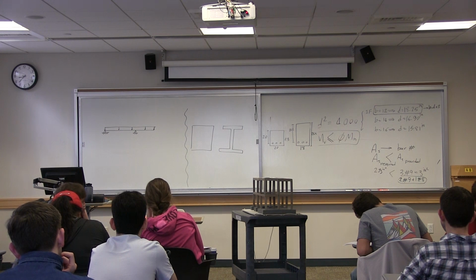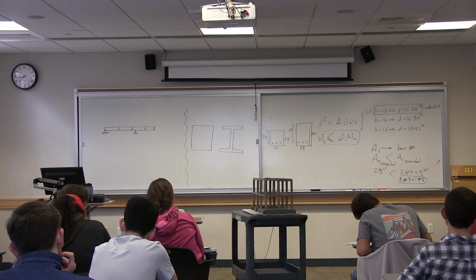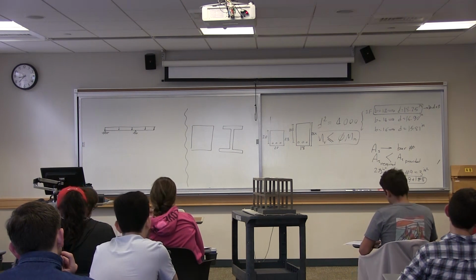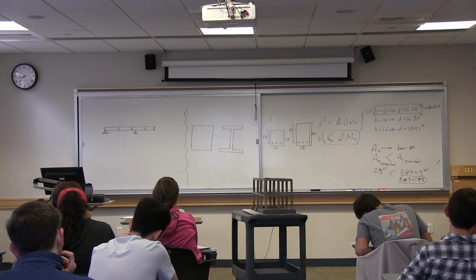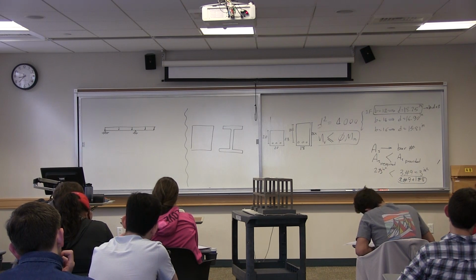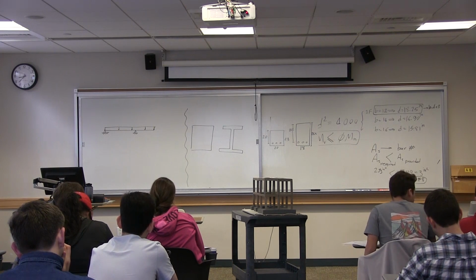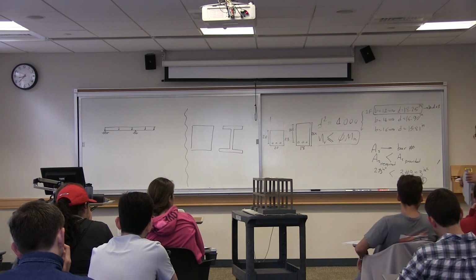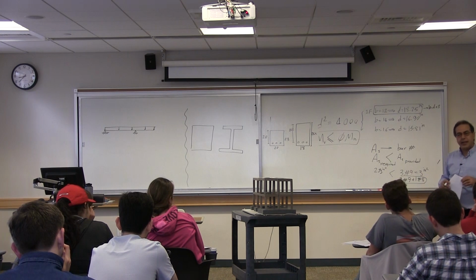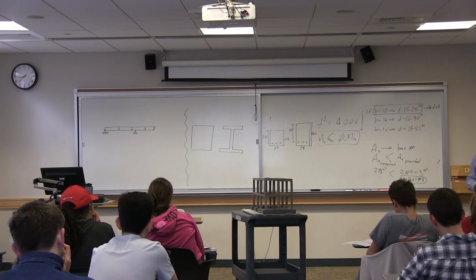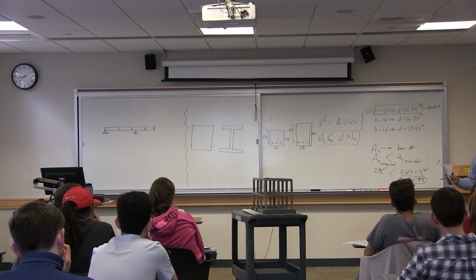When you design a beam, what is of interest is usually the maximum moments. Maximum positive moment and maximum negative moment. Do we put rebars only at the location of the maximum positive and negative moment, or everywhere? Everywhere. What do we do with other sections?